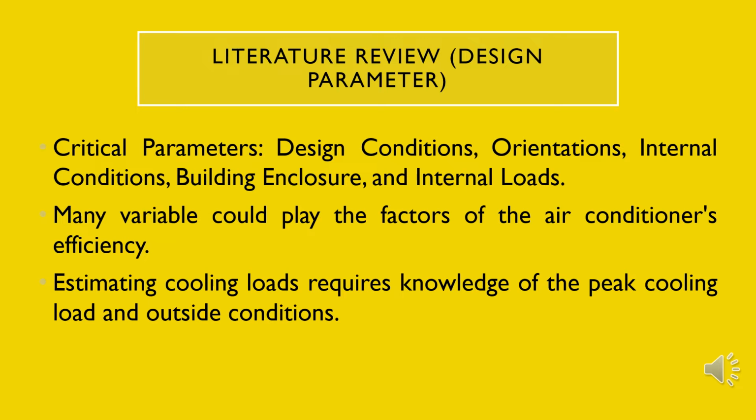desired temperature difference, type of construction, amount of insulation, number of shades on window, wall, roof, and size and surface area of the room, number of occupants, activity inside the building, amount of lighting, and number of heat generating appliances. These variables may impact the air conditioner efficiency. Estimating cooling load requires knowledge of the peak cooling load and outside condition.